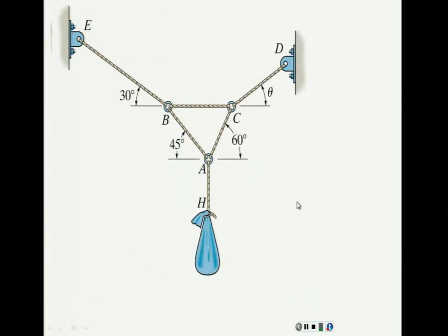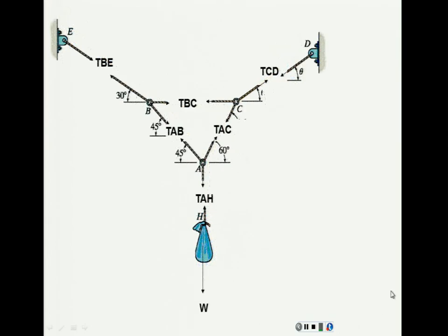So we have to do an equation of equilibrium. Where do we have to apply our free body diagrams? Everywhere. We need a free body diagram here, here, here, and here. If we do that, we have to draw circles and split everything in a way that is going to look pretty much like this. I don't know the weight, so we're going to express every single one of those forces in terms of that weight, which is my basic unknown.